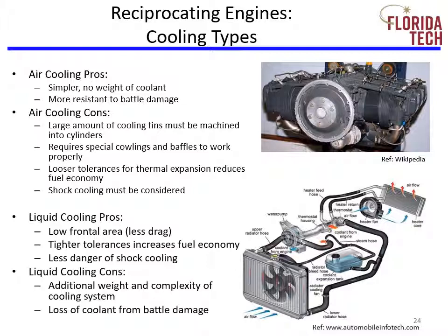However, we also use air to cool the engine. The airplane flies through the air outside. Air flows through the inlet usually found in the front of the airplane. The outside air is colder than the engine. As the air flows over the engine, it cools it in the same manner that oil cools the engine. This method of cooling can be severely restricted, however, when the airplane is running at high RPM and at very low speed, such as when climbing. Airflow is minimized, causing higher temperatures.